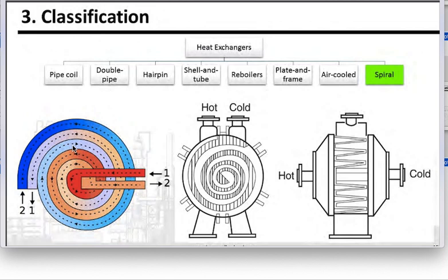A high heat transfer efficiency through this equipment, and compact design. If you are working in a narrow and limited area, you will find the need to install a compact design of heat exchanger like that, and the spiral heat exchanger will satisfy this need. It handles dirty and high solid fluids easily, like sludge and slurry, or fiber, or crystalline, and easy mechanical cleaning because of the curvature you will find through the tubes here, as you can see. Large hydraulic diameter, smooth curved flow path.